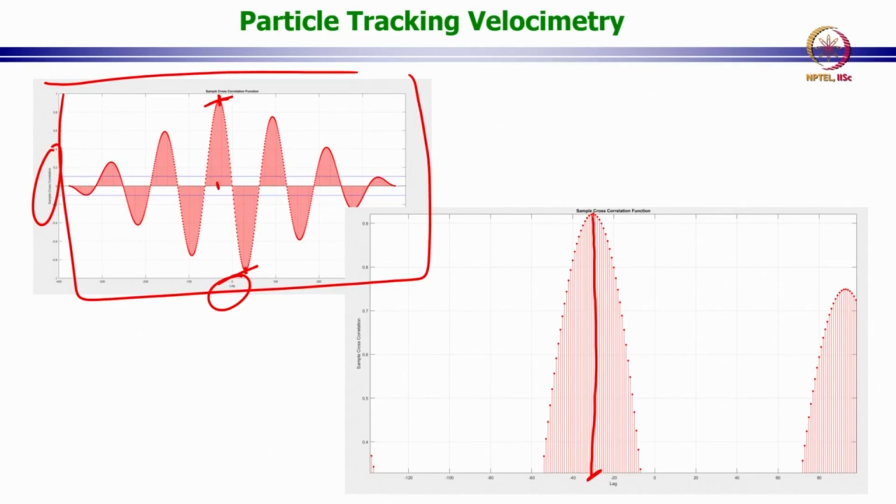So you can see that the cross correlation is telling you that at negative pi by 2, and you will have another one at plus pi by 2, there is a negative value of the sample cross correlation. Basically the cross correlation values are telling you that if you shift your signal by pi by 2, you achieve a very high match between the 2 signals.